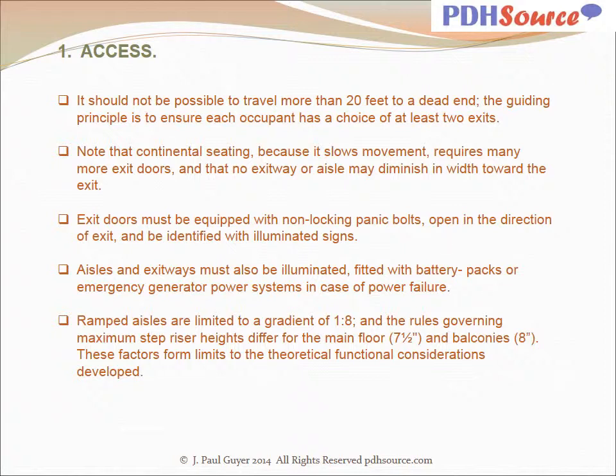Note that continental seating, because it slows movement, requires many more exit doors, and that no exitway or aisle may diminish in width toward the exit. Exit doors must be equipped with non-locking panic bolts, open in the direction of exit, and be identified with illuminated signs. Aisles and exitways must also be illuminated, fitted with battery packs or emergency generator power systems in case of